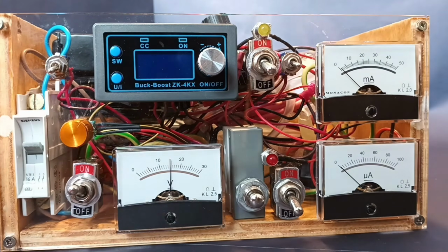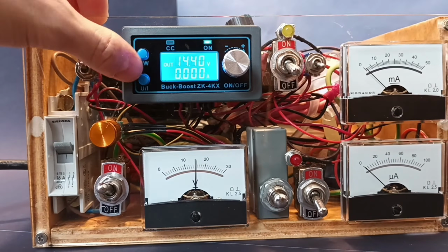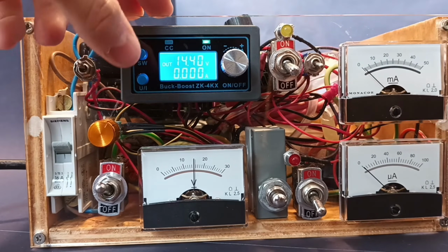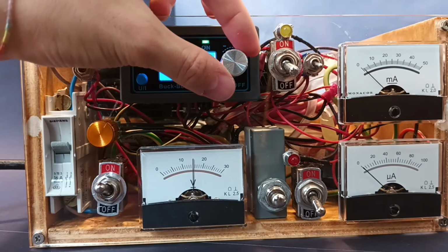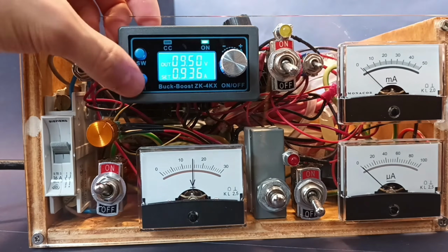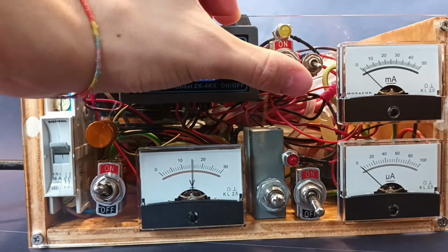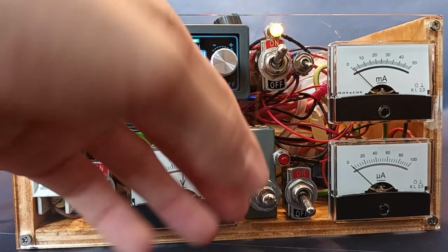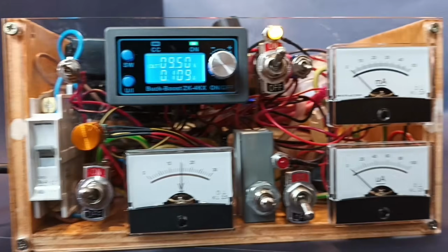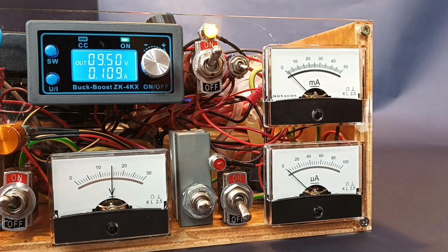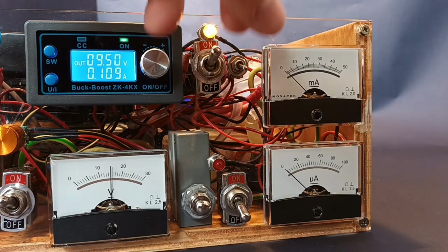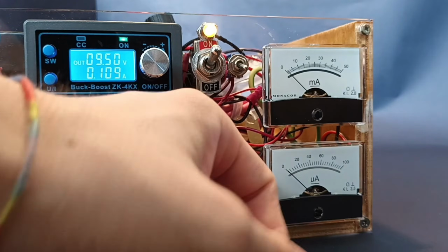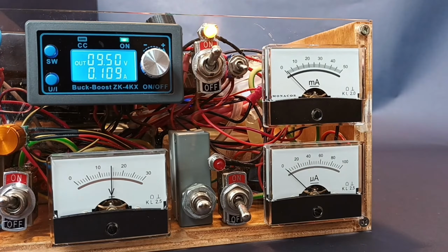Beside this part of the controller, there is this switch which feeds this DC-DC buck converter, which then gives power, when it's on, to this LED. As you can see, I can regulate the power from around 5 to 20 volts. And when I turn this on, the lamp also turns on, and this feeds the filament of the X-ray tube. This part here instead is only for the high voltage that also feeds the tube. And with this meter here, I can check the current flowing through the tube. And with this microamp meter, in reality it's a kilovolt DC that is being fed to the tube.